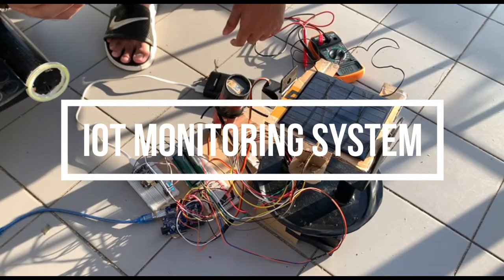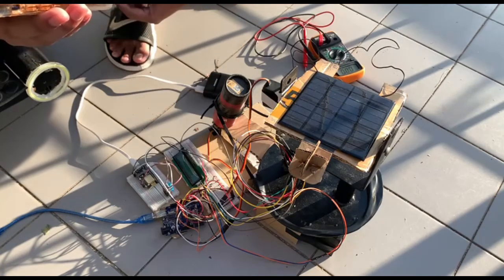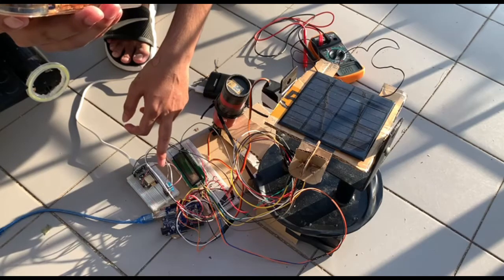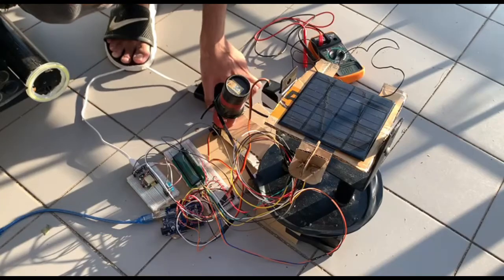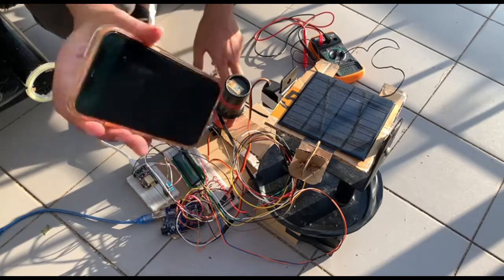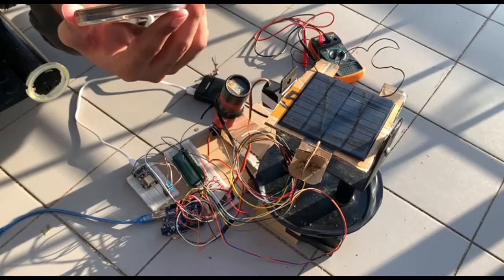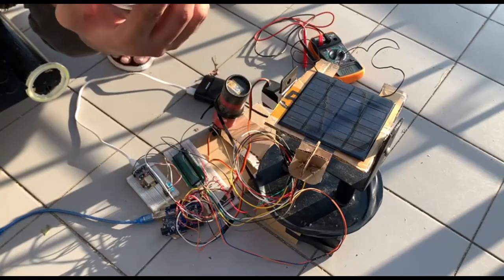For the IoT monitoring system, I am using the Wi-Fi module, which is the ESP8266, and the DHT11 as the temperature and humidity sensor. It is connected to the power bank, and it will send the data to the Blynk application, and it shows the temperature is 33.7 degrees Celsius and the humidity is 60.